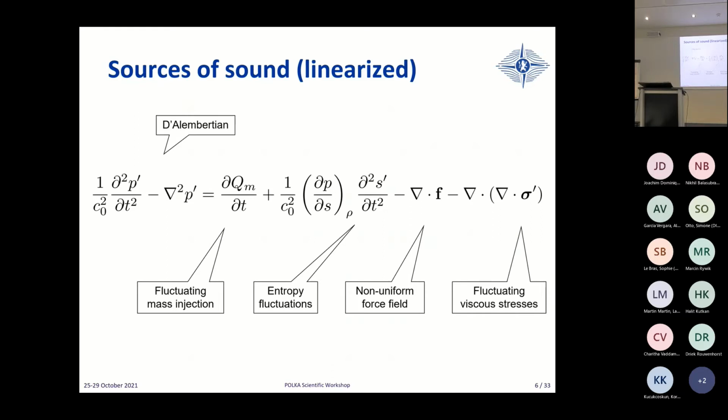Because when you have unsteady heat transfer, which is one of the mechanisms by which entropy is increased, if you have unsteady heat transfer to a fluid particle, when the fluid particle is subject to heating, it's going to dilate, it's going to expand because of the perfect gas law, if you want. So if you heat up a fluid particle, it's going to expand, and then it will gradually cool down by radiation, convection, conduction, what do I know? But eventually it's going to cool down, and therefore it's going to contract. And then you replace it by fresh fuel-air mixture. The flame front is passing again, it heats up and cools down. And you retrieve the idea of the pulsating sphere.